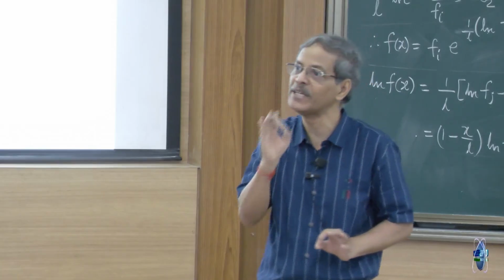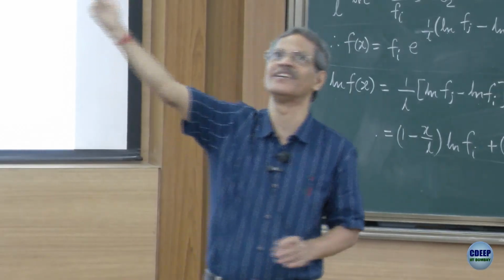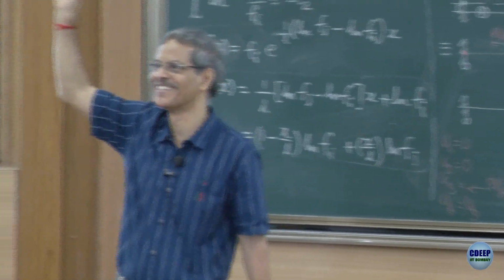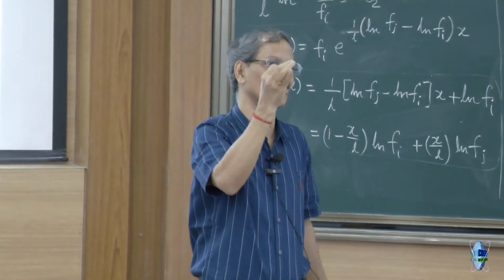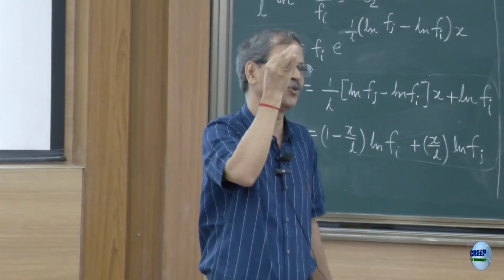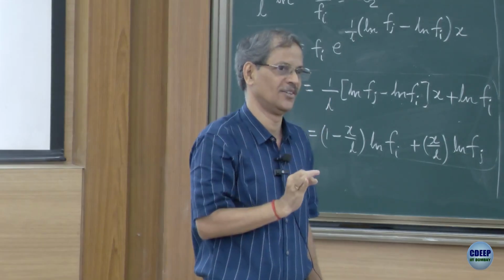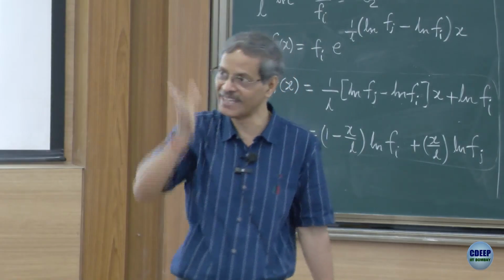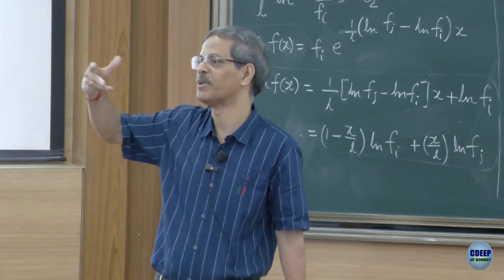So, when you are attempting finite element analysis for real world problems, like for example, this room's ceiling you want to model, see how many features are there in this. You have to take an intelligent judgmental call. Are all those geometric features important to model or not? Are they going to be in critical regions? Will failure happen there? Will critical buildup of temperature happen there?